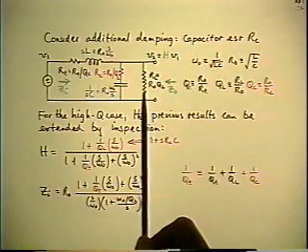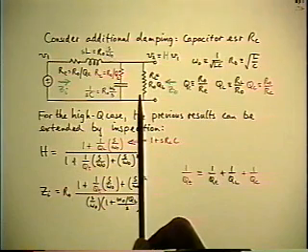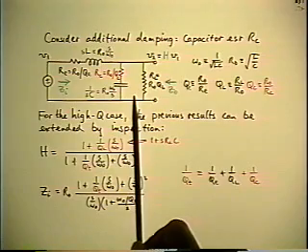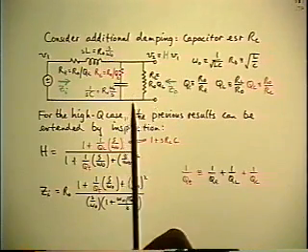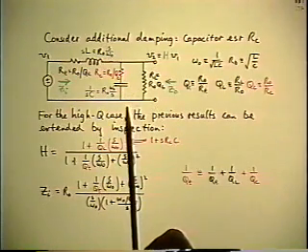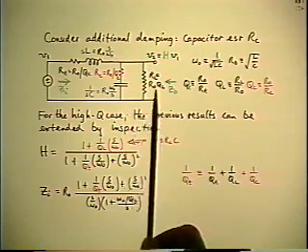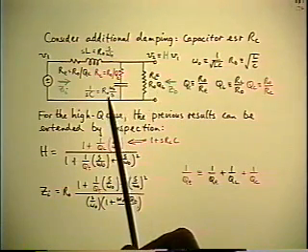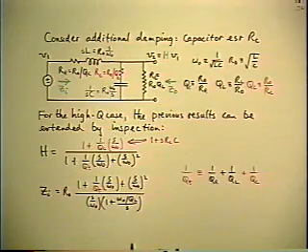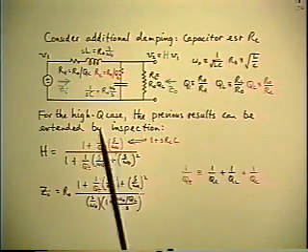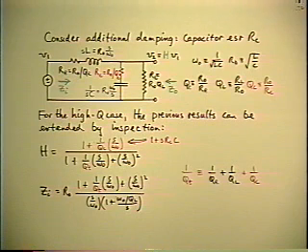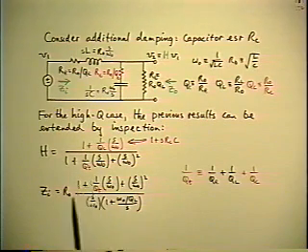Of course, you're going to pay a price if you're trying to generate a more complicated result by guesswork. The price we're going to pay in this case is that we're going to neglect the second order effects before we even start. So we're going to assume that there's no change of corner frequency, no change of zero frequency asymptote, and the only thing we're going to look for is first order effects, which will be the total damping and possible new corner frequencies.